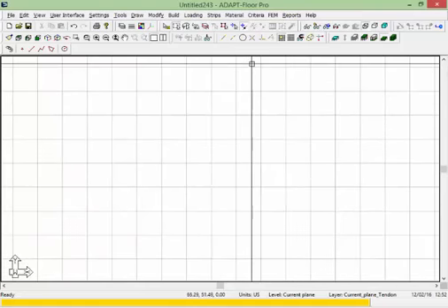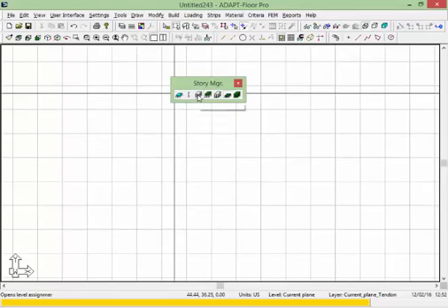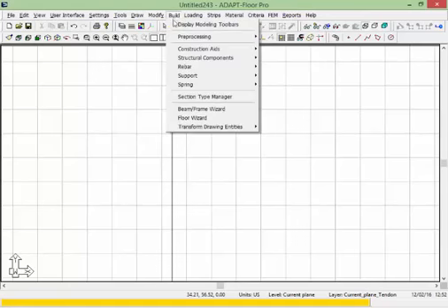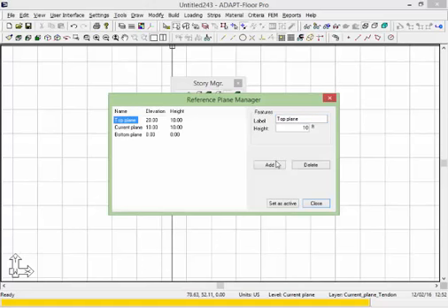In this example, we'll do a 5-story frame. So I want to use the Story Manager toolbar, and under the level assignment, we can also get here from the Build options, construction aids, level assignment, and here we're just going to add 2 more floors. So we'll go ahead and add 2 additional levels. I'll make this consistent in how these are named, so we'll call this plane 3. The current plane I'll rename to plane 2, and then bottom I'll just say is the base. And we'll leave the heights here to 10 feet.